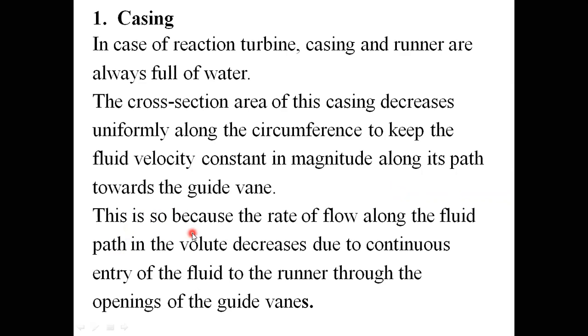This is so because the rate of flow along the fluid path in the volute decreases due to continuous entry of the fluid to the runner through the opening of the guide vanes.